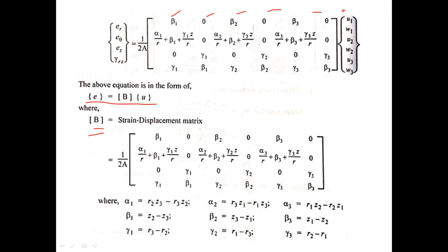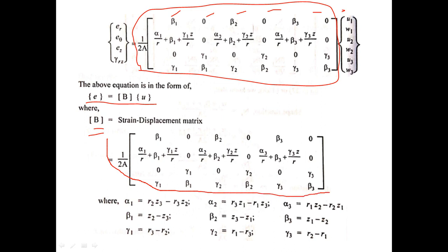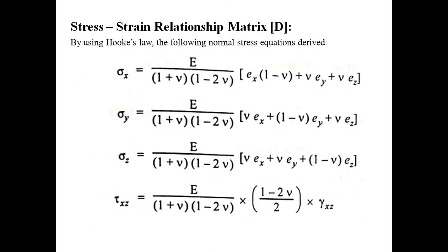Very good, r, θ, and z, isn't it? So we have to change those coordinates for convenience, substituting x equal to r, y equal to θ, and we get the above equation changed in terms of θ. So radial stress, circumferential stress, longitudinal stress, and the shear stress in the r z plane. We got the values like this, right?